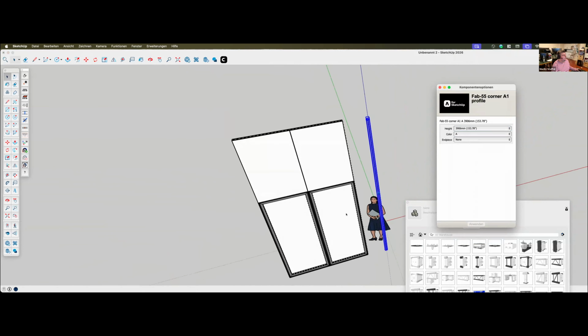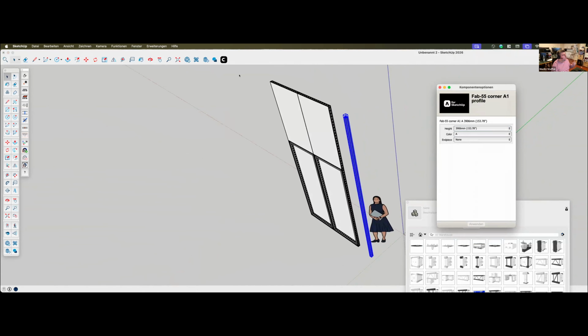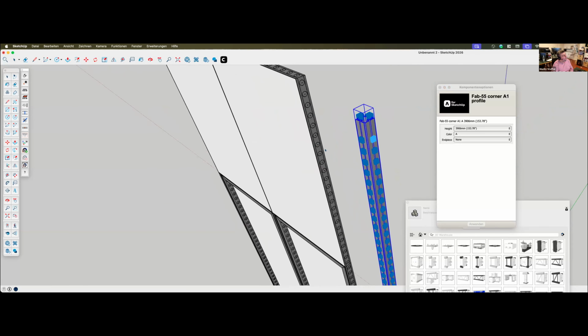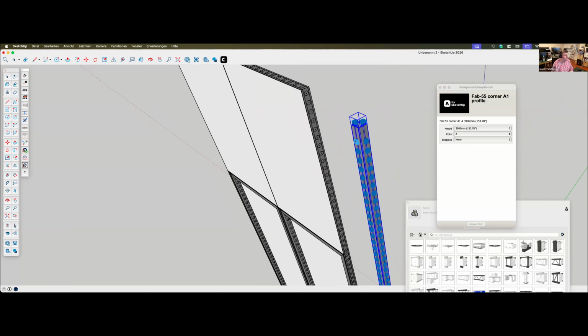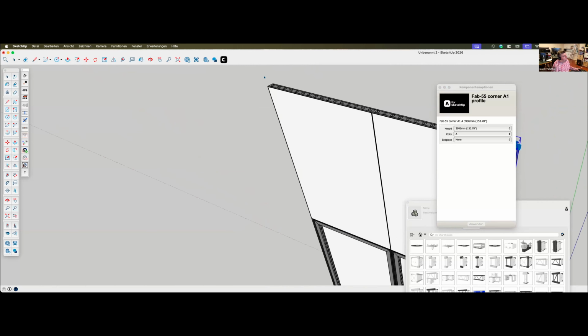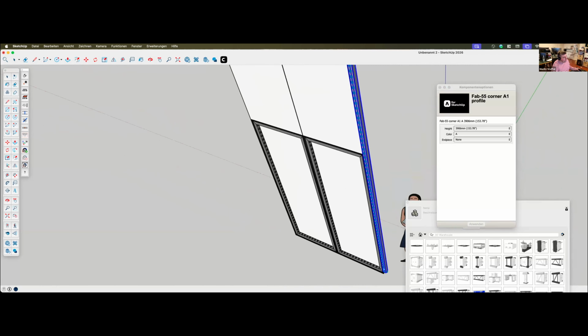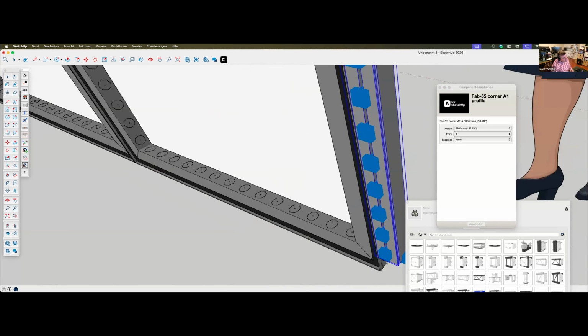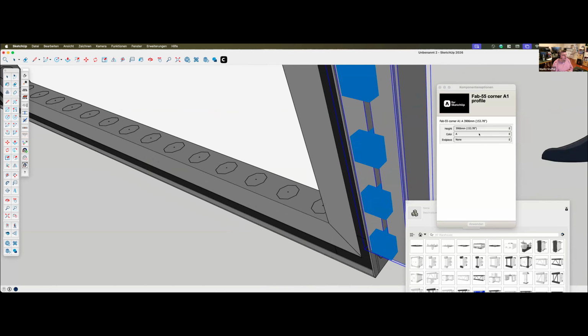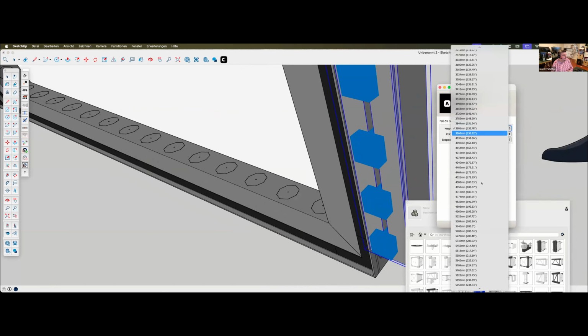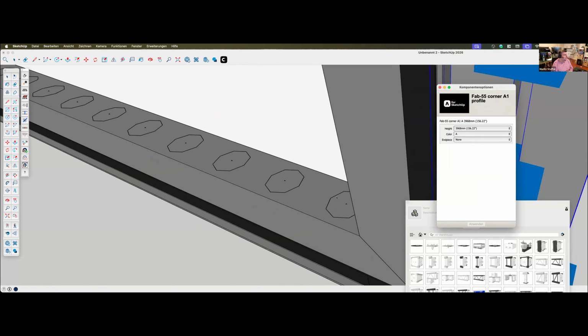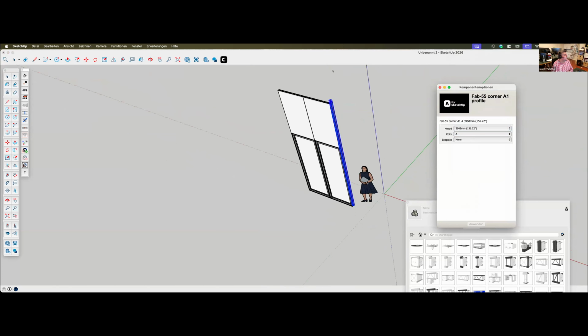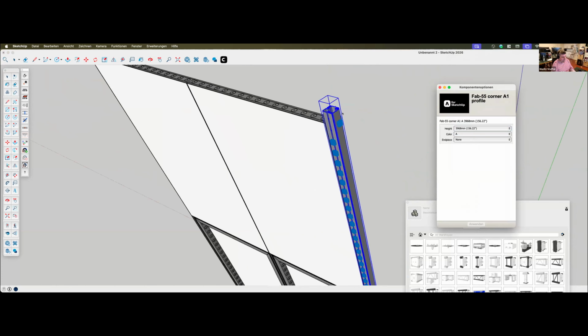Now I have my corner element in here like this. Again, I need to use the snapping tool like this. So I'm clicking on it again. So now it shows me where I actually can connect to it. So one click in here, one click in there, one click in here, one click in there, pressing enter. Now you see it automatically has inserted me correctly. I didn't select the right height. You see there's still one option in here, so I need to make it a little bit larger with this. So I'm applying this, and then I'm having a little bit of an overlap in here with this.